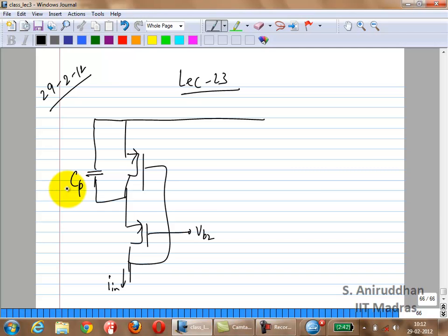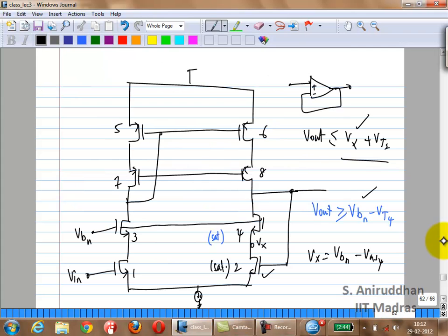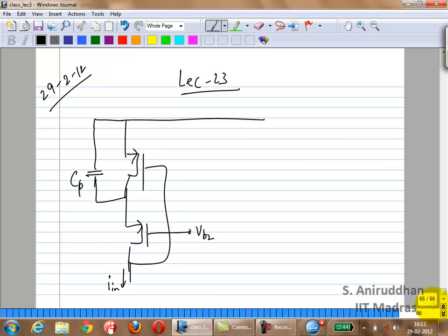First of all, what happens to the current? This is your signal current. So this is the cascode, right? This is the biasing part of the cascode, the mirror part of the cascode, and this is where you're drawing current. I've basically drawn this portion. What do you think is going to happen to the IN? Some portion may flow through the capacitor CP, correct? So what does that do? It flows through CP, that's fine, but that is not necessarily a reason for the pole to appear. So what are you trying to find here first of all?